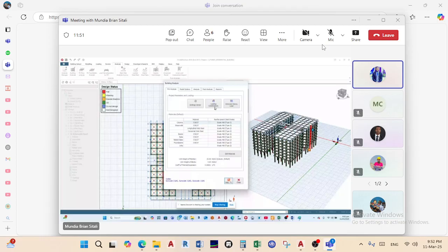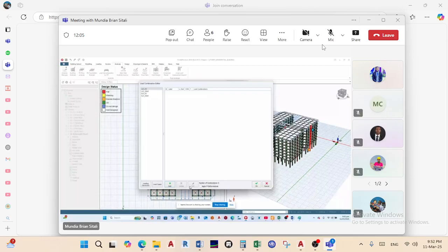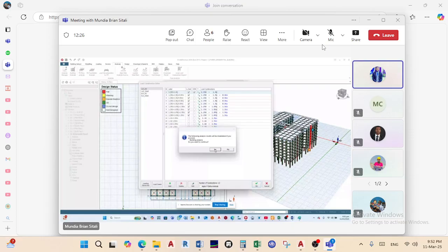We delete the loading generators and we generate just normal load cases for dead load and for live load, and maybe just wind as well. So we have just these load cases. What else did you put? I should think unassigned loads will be deleted, yes. So we'll analyze again, but it will take a lot of time. This also sometimes